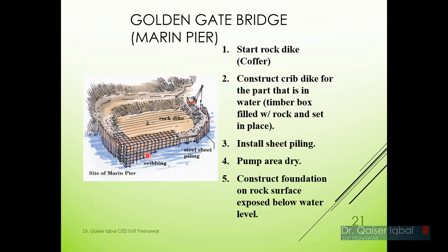So it will basically keep the water out as well. At the same time, it will give stability over here, so you can make excavation. And on this side, they use sheet piles over here, you can see, which are made of steel. Sheet piles are being inserted over here.